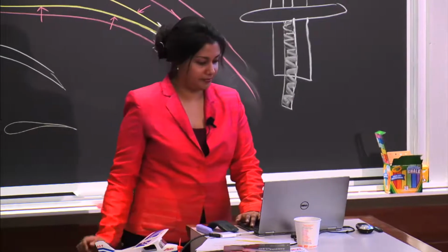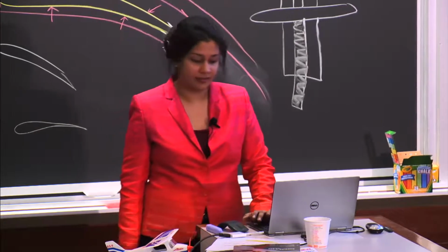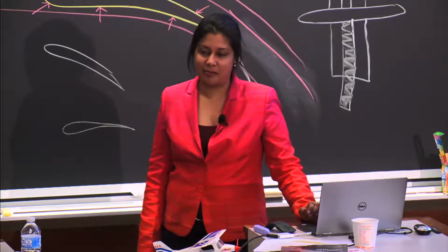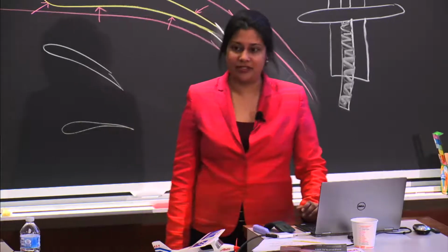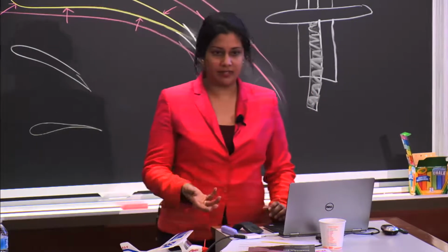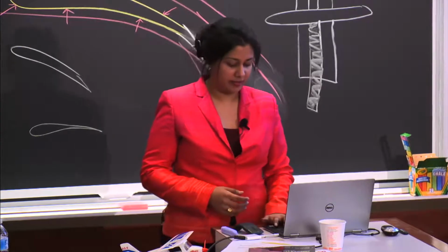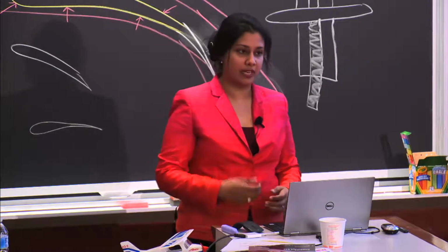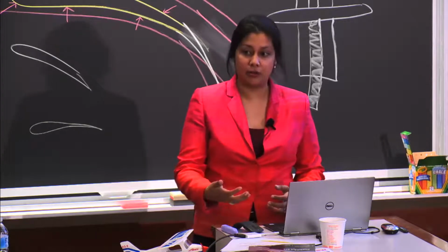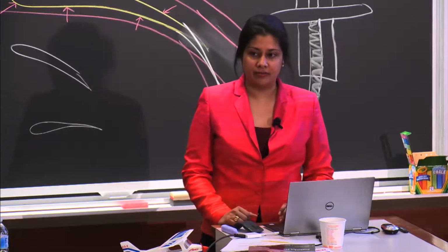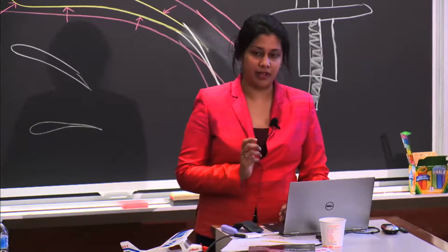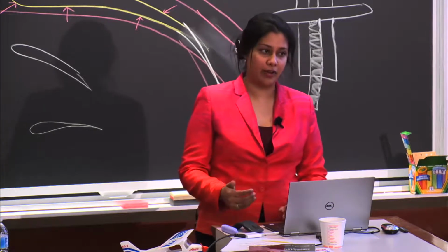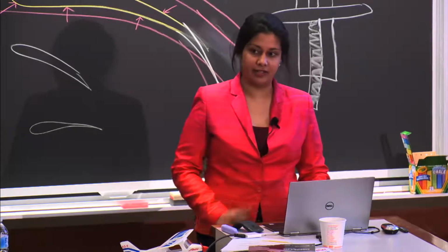Thanks. I have a simple question for you, maybe. Just to help me remember, why is it called P factor? What's the P for? Power or propeller. So the P is referring to that propeller, right propeller more than the left. It also usually happens when you're at a higher power. So some flight instructors like you to think about when you have higher power in the airplane, you'll need to put on more right rudder to counteract that left turning tendency.